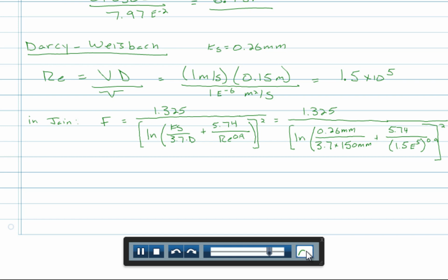So we get from the Swamee-Jain equation that the f value is 0.0240. And so that's the roughness value for these specific flow conditions, meaning for this specific pipe diameter, for this flow velocity, and for the temperature of the water, which factors into the kinematic viscosity. Neither the Manning's equation nor the Hazen-Williams expression takes any of those factors into account in generating roughness values.